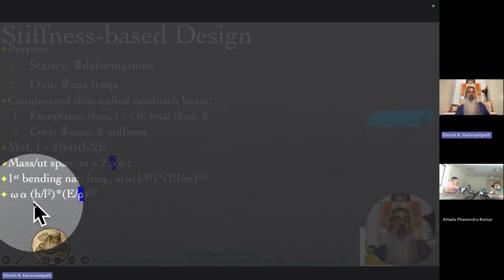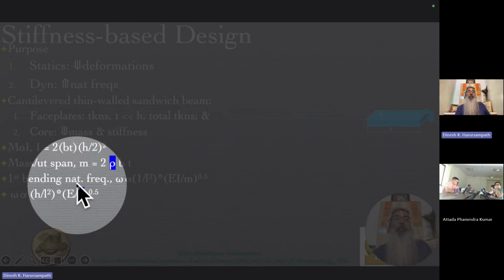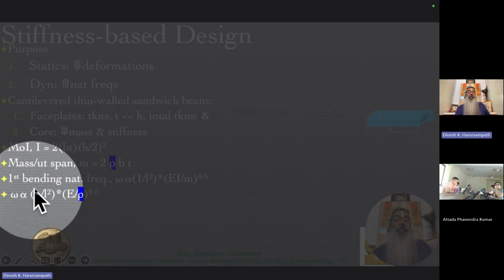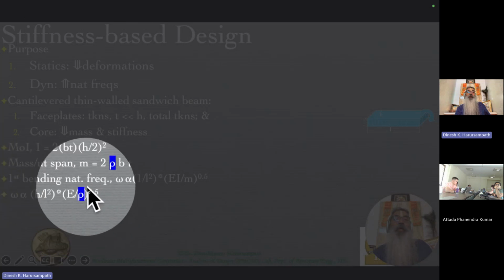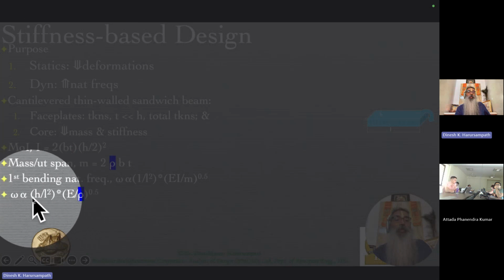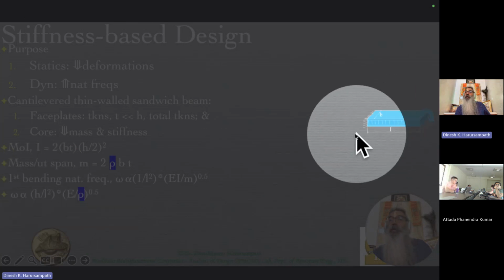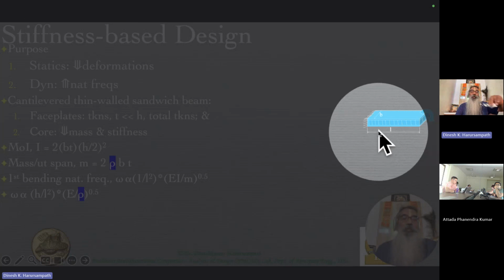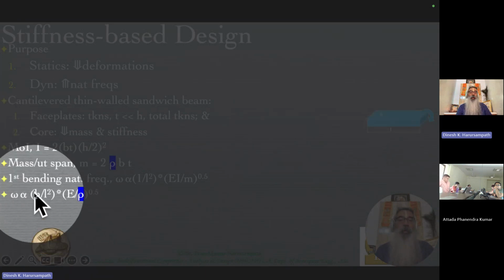in helicopters and similar kind of potential accidents in the case of fixed wing aircraft or any other flying vehicle for that matter, which means that either I can do it through increasing this first factor through geometry or the second factor through the material. Let's focus on the geometry. Once again, L is involved here, which is the semi-span, which is something the aerodynamic team will never allow me to change because that is something that we need from a particular planform area which is required and the other aerodynamic requirements. So we will not have any room to play around with L.